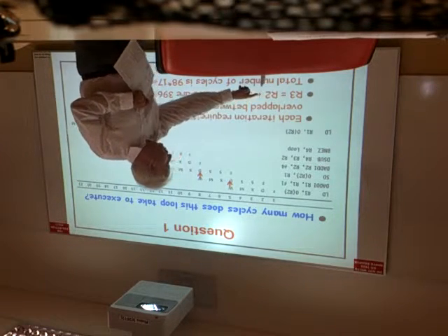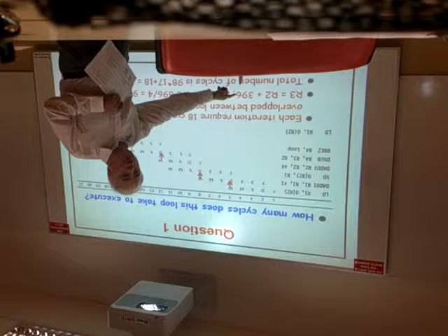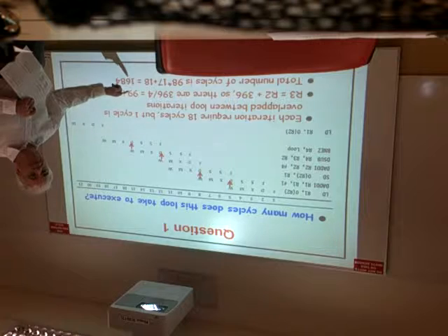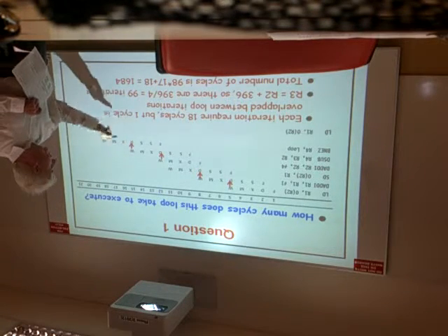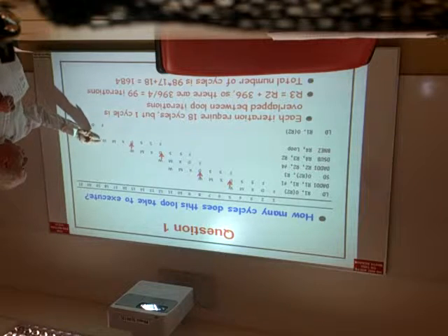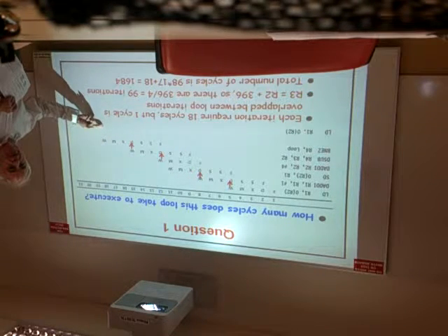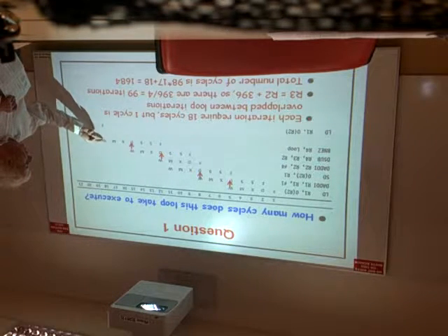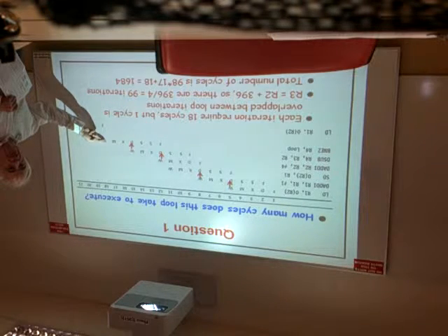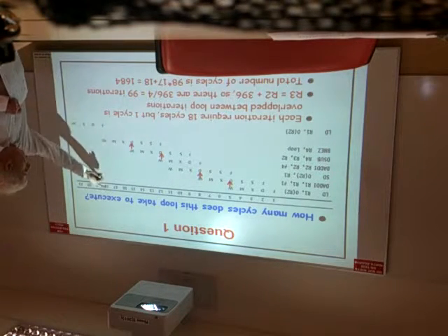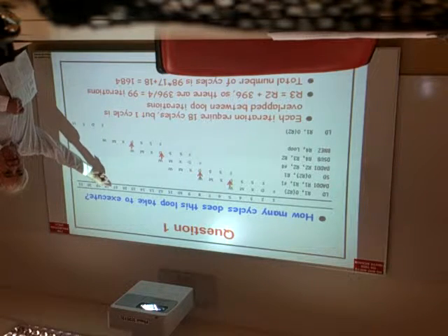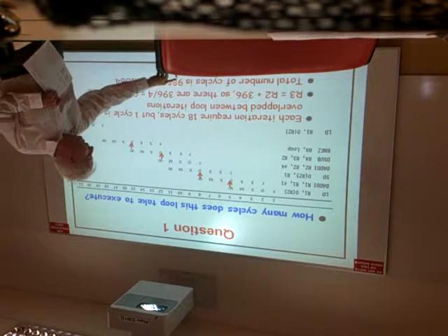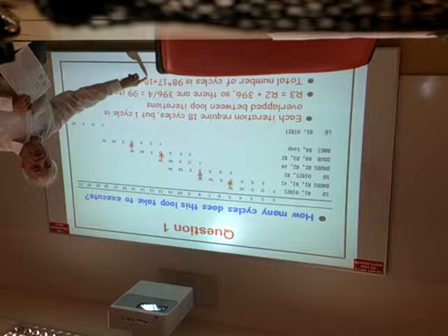The difference between R2 and R3 is initially 396, and we subtract 4 each iteration, so therefore there are 99 iterations altogether. For all except the last iteration, we can overlap one cycle of one iteration with the next iteration, okay? Because we can start to fetch the instruction during the execute, in the same cycle as we write back the register. That's 17. So for all except the last iteration, there are 17 cycles. We have 99 iterations altogether, 98 of them take 17 cycles, and the last one takes 18 cycles.